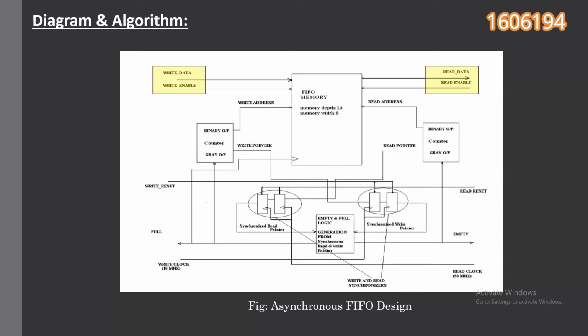As soon as the first data word is written to the FIFO, the write pointer increments. The empty flag is cleared. When the write pointer wraps around all memory and catches up to the read pointer, the full flag goes high. Now, if the read pointer goes high, it starts to read and the full flag goes low. After reading all data, the empty flag goes high.